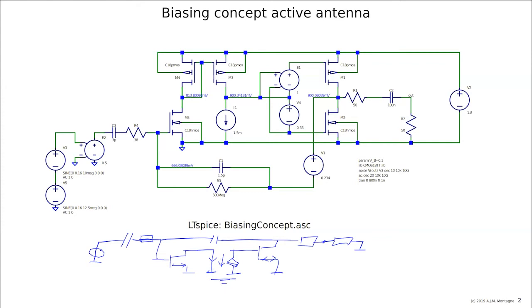And here in this schematic, you see there is no decision how to make the current mirror. Here you see the current mirror is made with P devices. We could also make it with N devices, but then we get a kind of folded construction, and that would cost us more current. So here you see it with P devices, and the P devices should be designed such that their GM is much lower than that of the N transistor in order to get a low noise contribution. That is already what we have discussed during the course before.